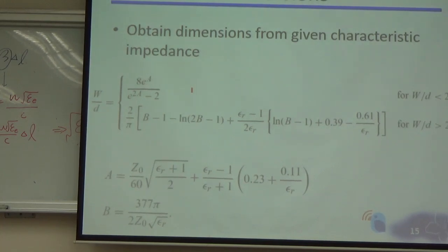Maybe I will give you some dimensions you are used to in your project, the width and the thickness and the FR4, and you calculate what the Z0 is for that. For those numbers you're familiar with, you can check the result against what you are using every day.